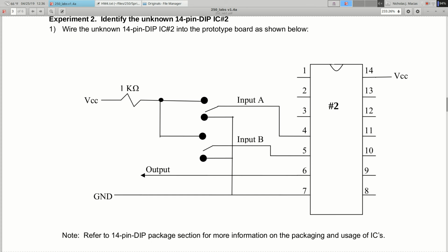And if we had a switch that you could move between 2 points, we could implement this circuit as we see it here. Right, so that's a double pole single throw switch. We don't have those. All we got is a switch that either closes or opens, not a switch that connects the input to one of 2 points. So we have to fake that.